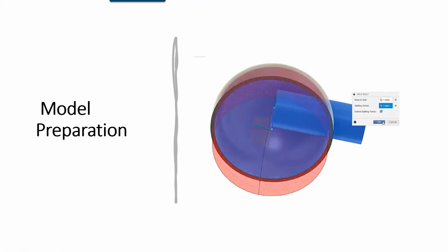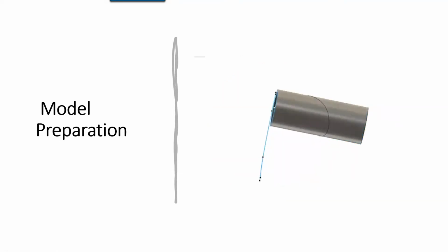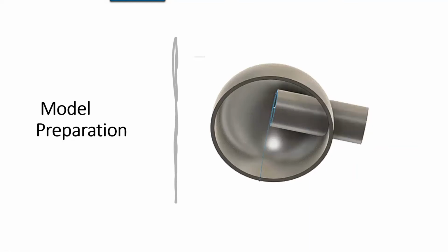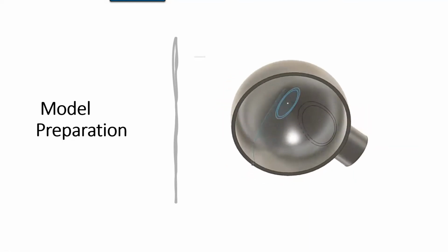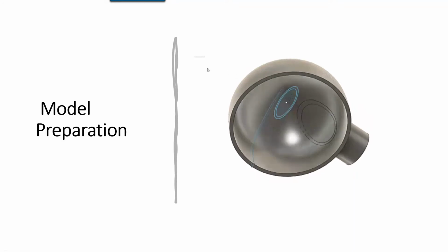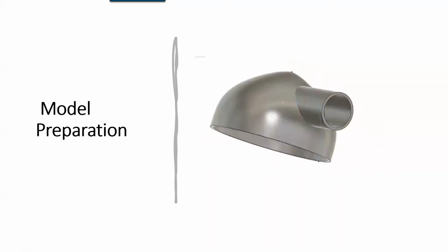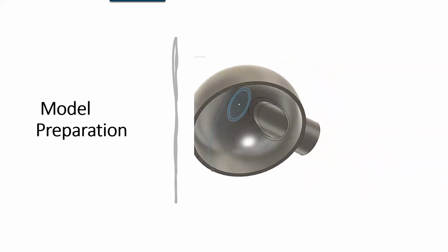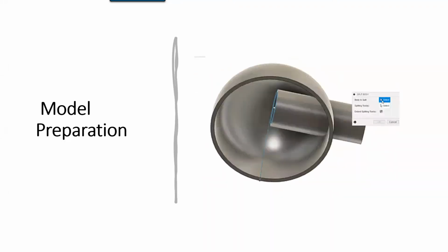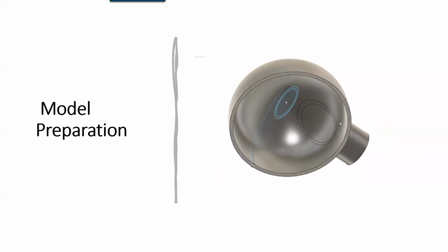All right, and then the last one that we mentioned is going to be the split body. It's exactly what it's referring to: you're selecting a surface, and then you're splitting a specific body. What this allows you to do is create the exact geometry that you want without necessarily having to create reference sketches. What you could have done here is create an outline of the ID, the inner profile, and then do a revolve cut. But why do that when you can just take advantage of a surface that's already there, split the body, and then remove the body that's not needed moving forward? So many different ways.